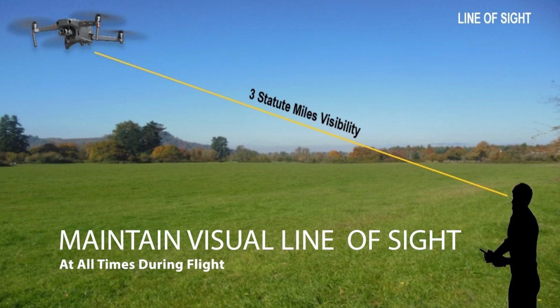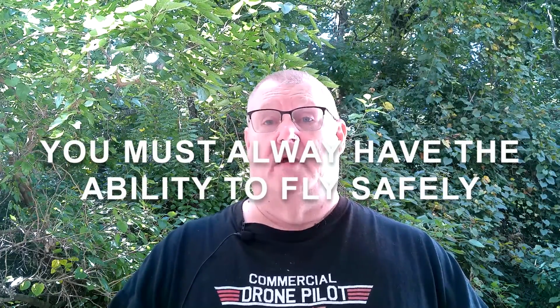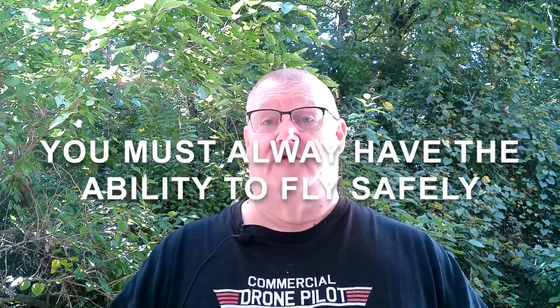In addition, you must have at least 3 statute miles of unobstructed clear visibility between your launch point where you're controlling the drone and the drone that's in the air. The FAA requires that you keep the drone in sight at all times during flight. Finally, the weather conditions must be such so as to allow you to always operate within acceptable safety parameters.